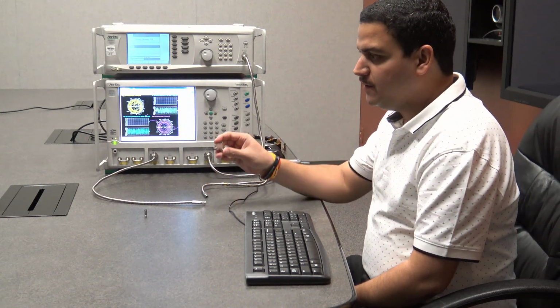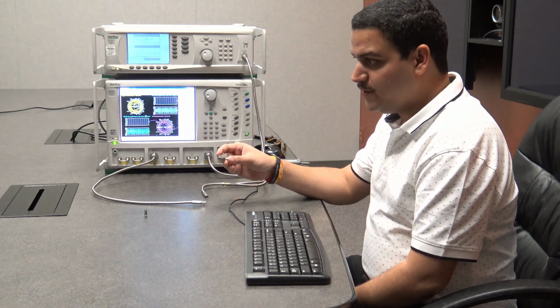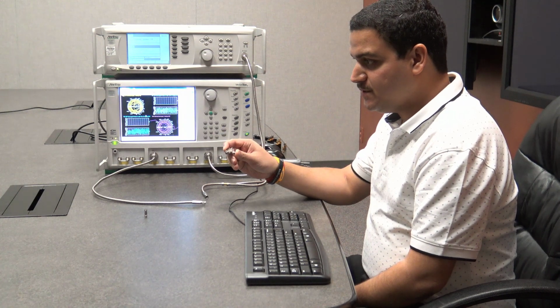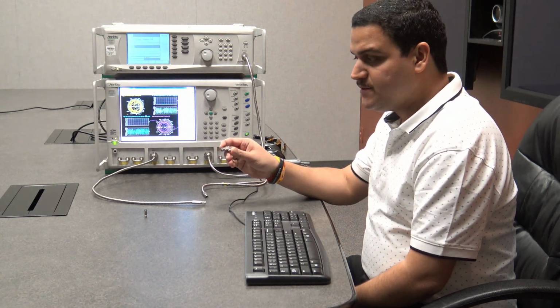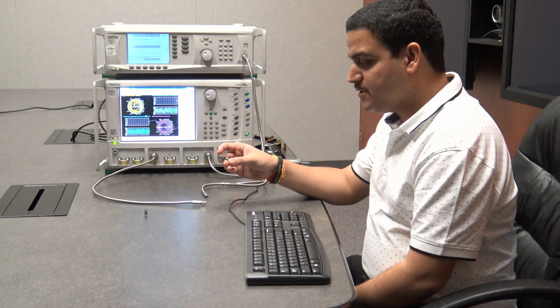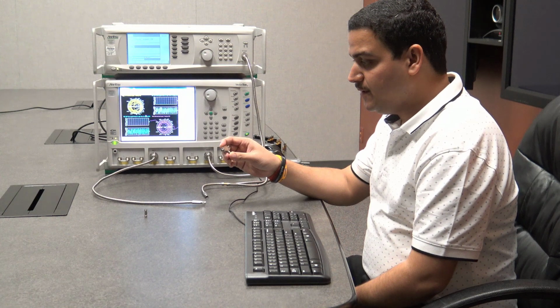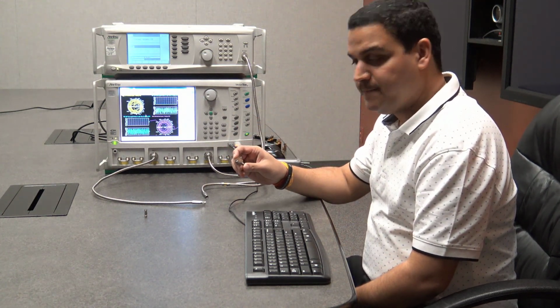So today we are going to make some mixer measurements. This is the mixer, and the specification for this mixer is RF or LO can take 2 to 18 gigahertz, and the IF operation is from DC to 750 megahertz. I will be displaying the graph and measurements of this mixer as per its technical data sheet, and then we will compare it with the measurements that we are making today.